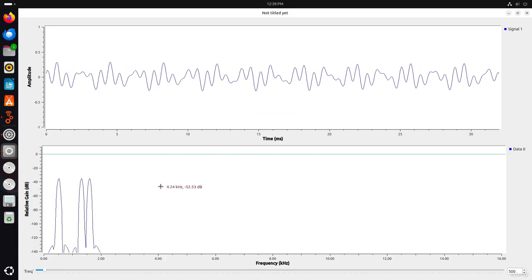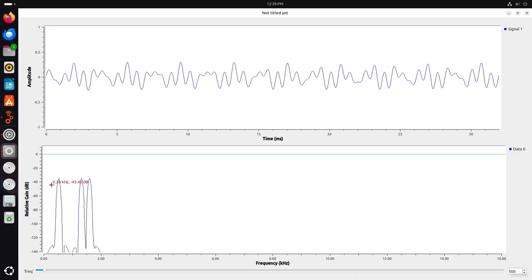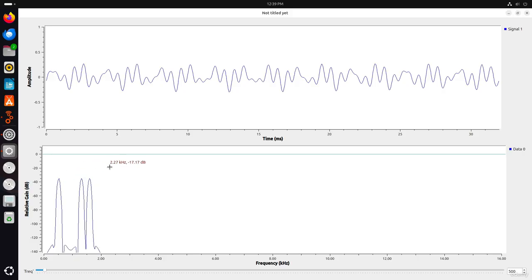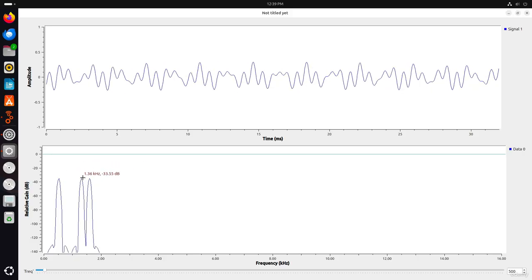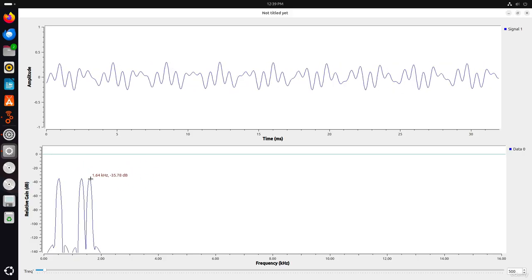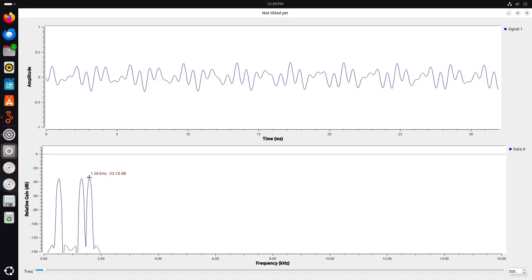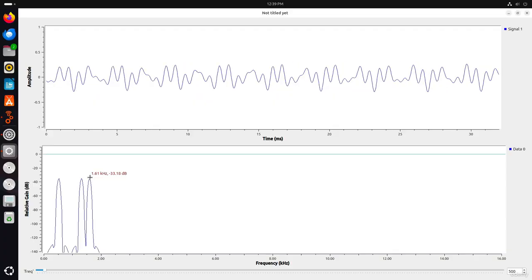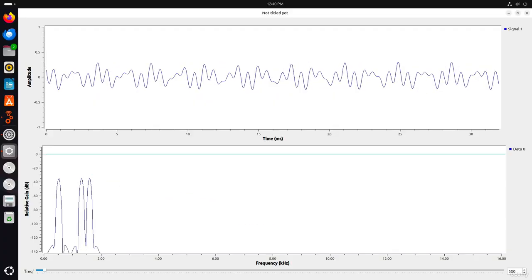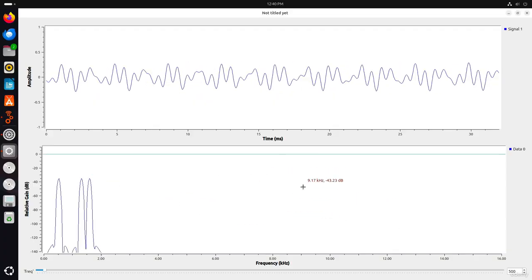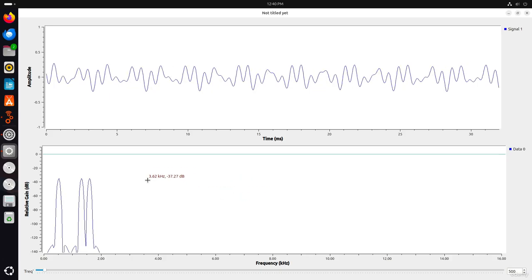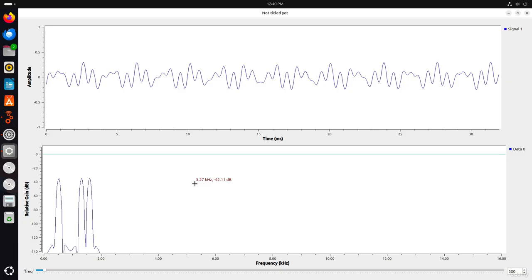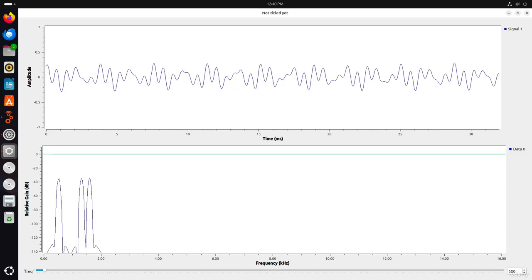And the frequency plot will display three distinct spikes at 523.25 Hz, 1318 Hz, and 1568 or 1600 Hz. So after executing this flow graph, the frequency sink displays the frequency domain representation of the combined signal. So this plot provides insights into the signal composition.